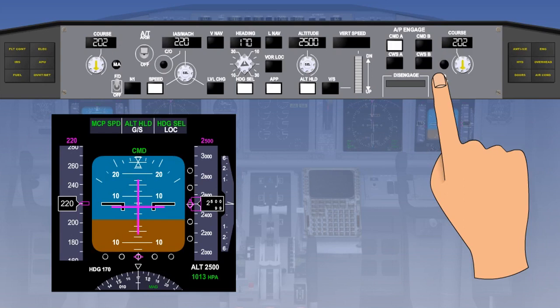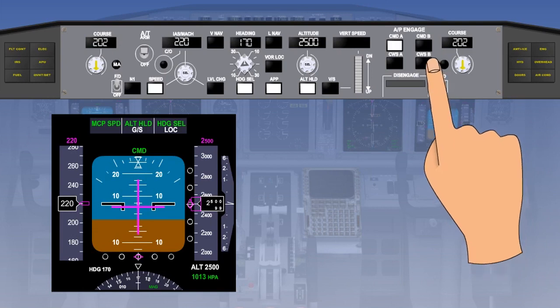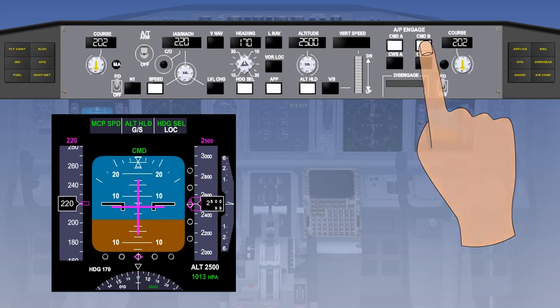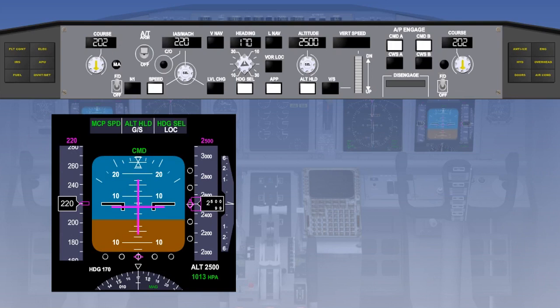Any time after approach has been accepted by the autopilot, the second autopilot can be engaged. In this case, Autopilot B is the only other autopilot available. This means it is a fail-passive system, as you cannot continue with an autoland approach should one of the autopilots fail.